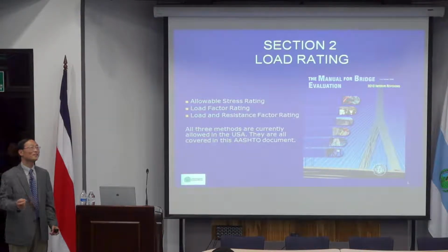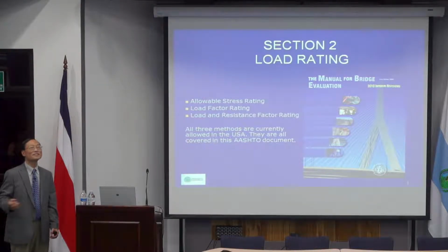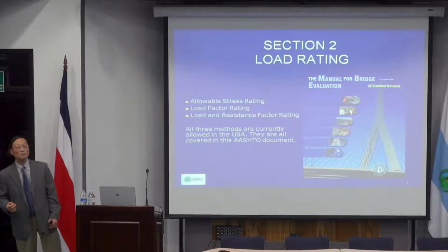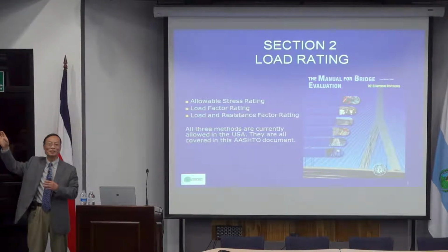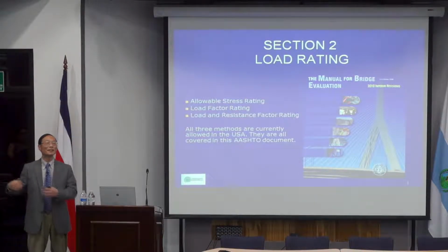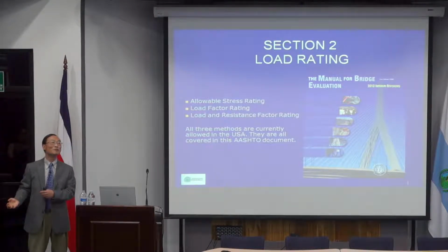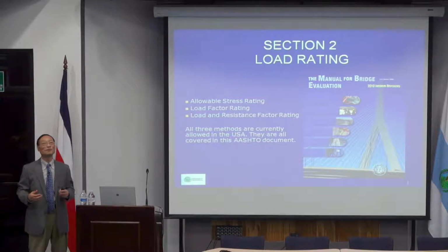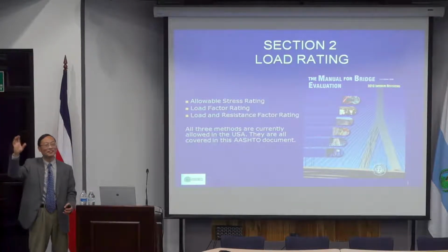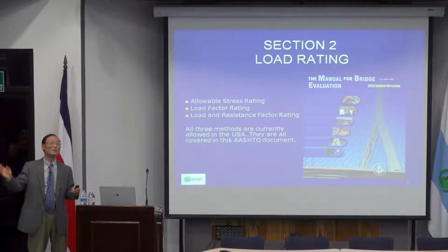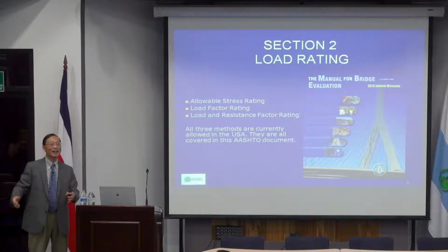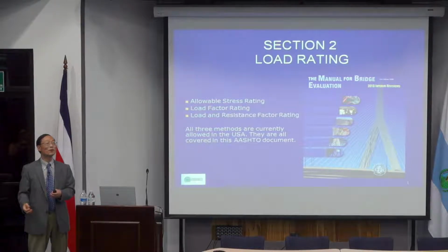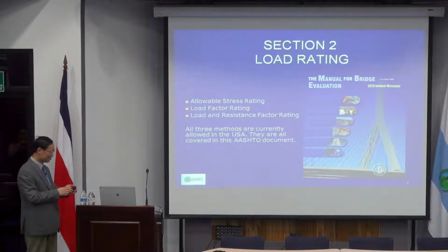So what is a load rating? A load rating is just a reverse of bridge design. When we design a bridge, we know that a bridge has to be designed for this loading. So we know the loading, and we try to select the member sizes to satisfy that loading requirement. And when we do load rating, it's just a reverse. Load rating is always for the current structures. If I see a bridge, I know the girder sizes, I know the deck, I know how much reinforcement is inside, and so on. So all I need is, I want to know how much load that particular structure can carry. So it's just a reverse of the whole process. That's what load rating is about.